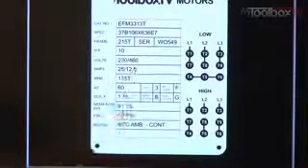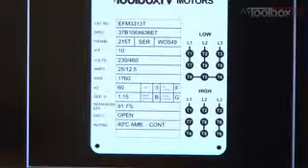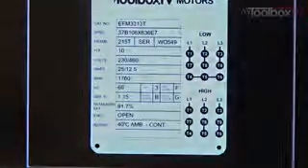There's lots of advantage to running this motor on 460 volts rather than 230, and one of those is wire size. 12.5 amps is going to require smaller wire than 25 amps would, and a smaller breaker, and less heat loss in the conductors going out to the motor as well.